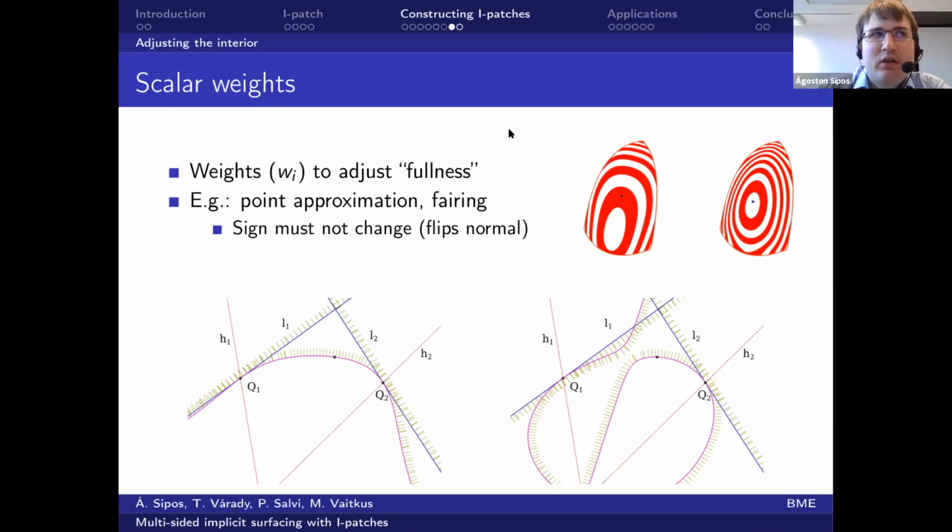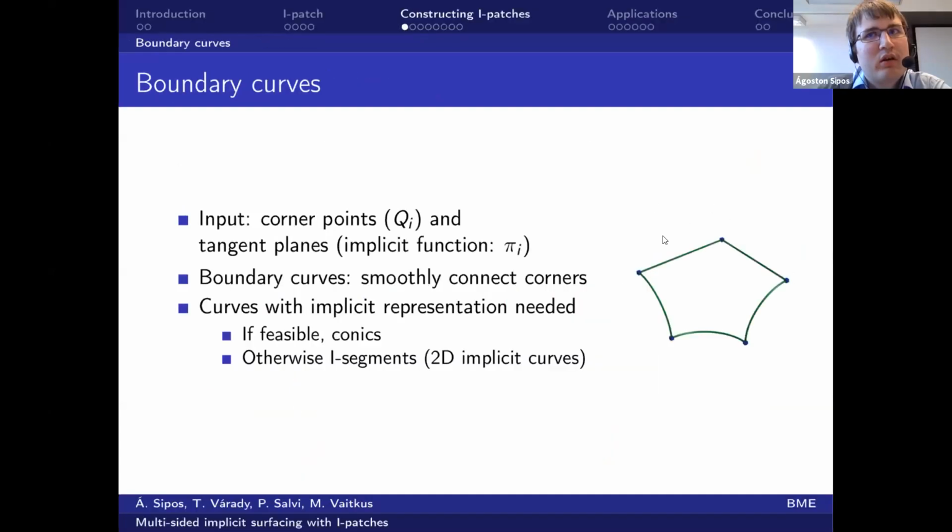What we did is that we took advantage of the fact that we know all the corner points, and as we know all the corner points, we can just fit a very simple parametric patch on the corner points, and then triangulate the parametric patch, which is a relatively easy task, and then project each of the parametric surface's points on the implicit patch. And of course, if it did not work for some reason because the parametric and the implicit patch were too distant from each other, then we modify the parametric patch.